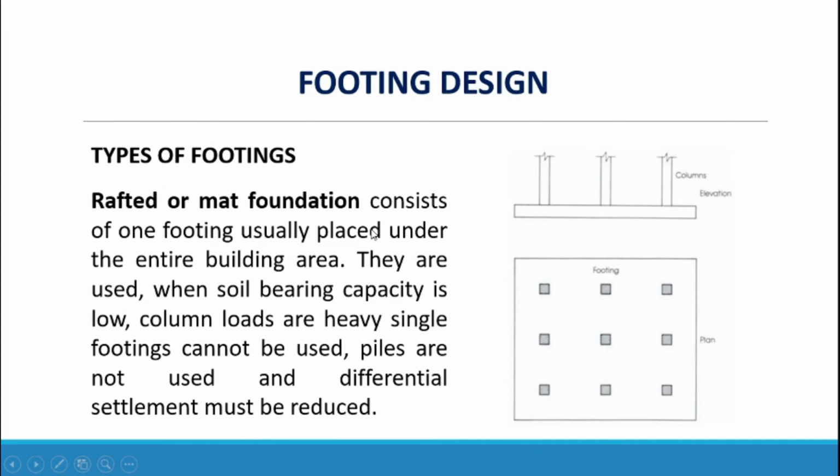Raft or mat foundation consists of one footing usually placed under the entire building area. They are used when soil bearing capacity is low, column loads are heavy so single footings cannot be used, piles are not used, and differential settlement must be reduced. And that's a mat foundation.